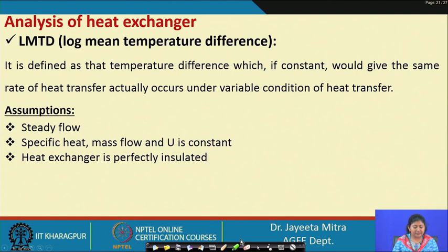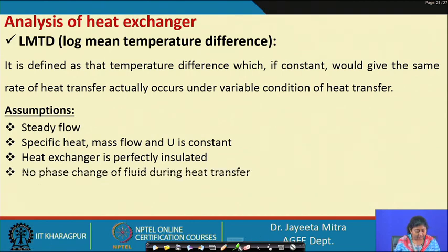Then the heat exchanger is preferably insulated, that means we consider that there is no heat loss to the ambience. Whatever heat the cold fluid is getting is coming directly from the hot fluid. Also, no phase change of the fluid during heat transfer. The heat transferring causes sensible change of both fluids, no latent heat or phase change is involved.